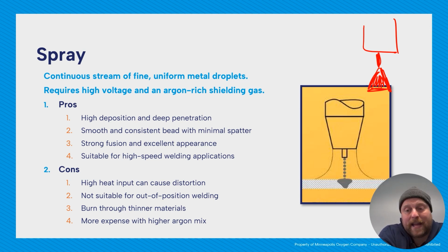It's very high heat input, so you do have to be careful. If you're going to be doing a long time, you're probably going to need a water-cooled torch, so you're not going to melt any torch component. I've seen people get too close when they're welding and either melt their cover lens or part of their helmet. People have told me that it can get so hot that it can crack your filter lens if you're too close. This is where you'd want to have extra heat pads and things like that for your arm that's closest to the welding. So tons and tons and tons of energy are going to be used. Also, definitely got to make sure you change your filter lens, all that sort of thing.